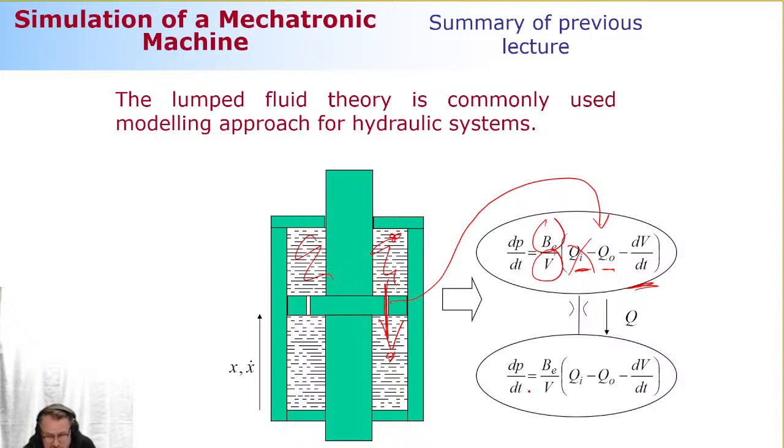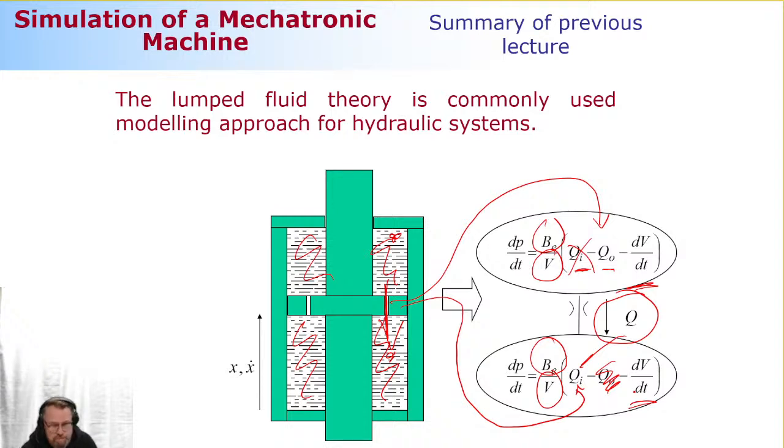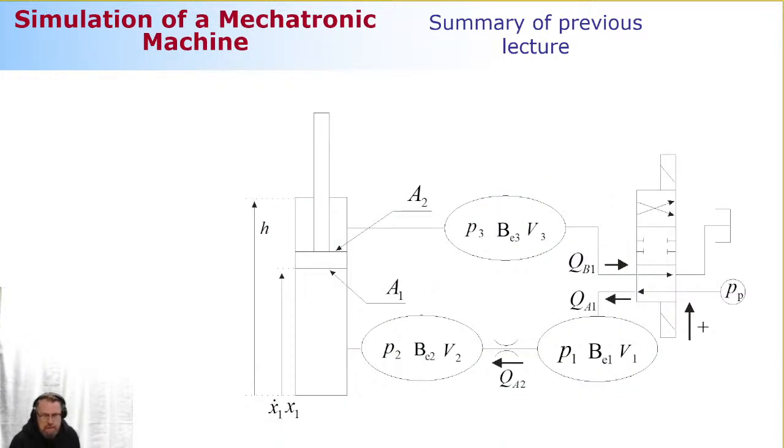And then here, I have the same equation, but with different parameters. Now I have the effective bulk modulus describing the fluid in the lower part of the damper, and then I have the volume size itself. And now this one here is the one that is coming in. You see, here is a positive direction, so this one is coming in. This is nothing, so nothing is going out. And then this one is describing the volume size. Okay, right. Here's another example about discretization.